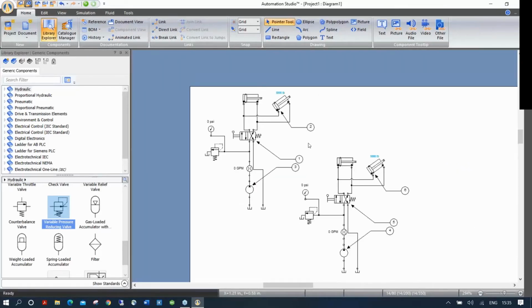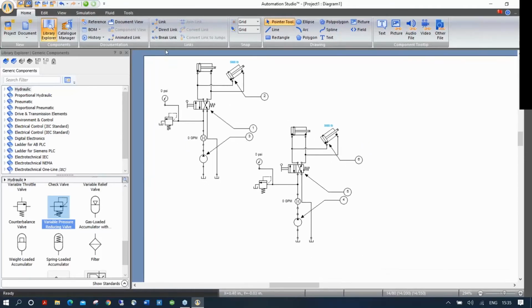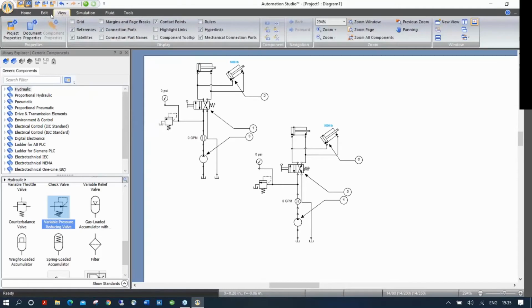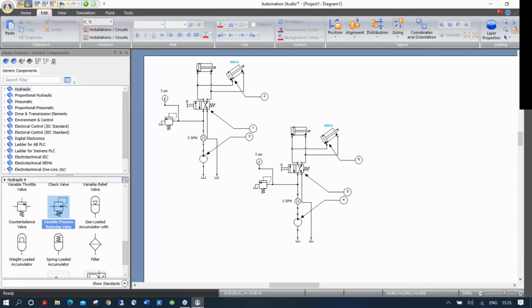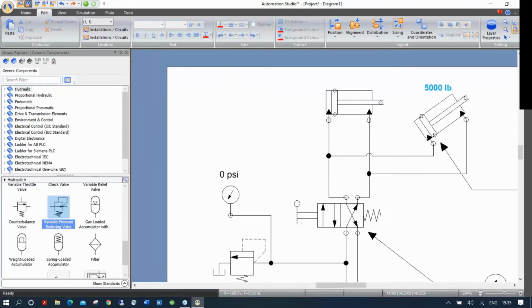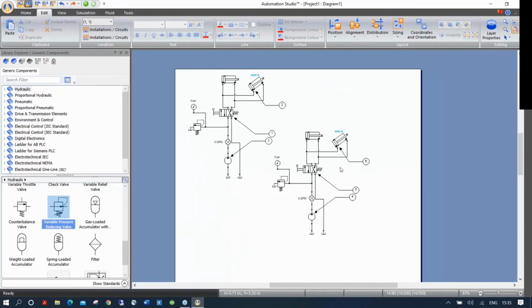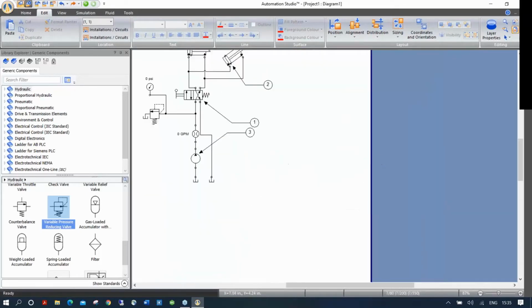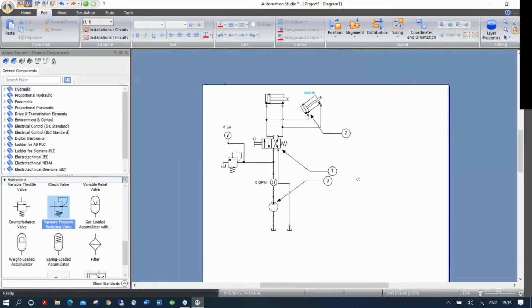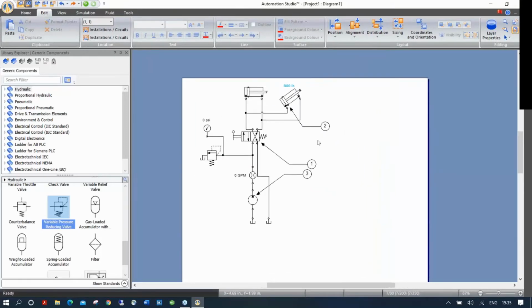By the way, we have the possibility to undo things in Automation Studio. So if you go in the View tab, Edit, okay, there's arrows here. You see Undo. You can click here to go back, or Windows-based, Control-Z, Control-Z, Control-Z, Control-Z. And you see this is one more time. This was my original size, and back, this is my 100%. So if you make moves on your drawing, on your schematic, and you say, oh boy, I think it can go back up to 20 moves. So this is good to know, okay?